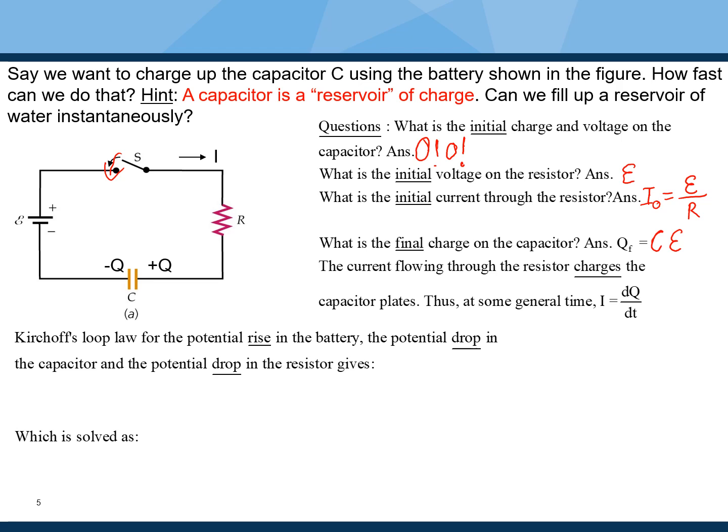And if we have current flowing in the direction shown in this circuit, then this current will contribute towards building up the positive charge here. So we can assert that I is equal to dq by dt. I is of course always equal to dq by dt, but it is important to understand that when we assert it in this formula, what we're essentially saying is that the current is equal to the rate of increase of charge on the plates of the capacitor.